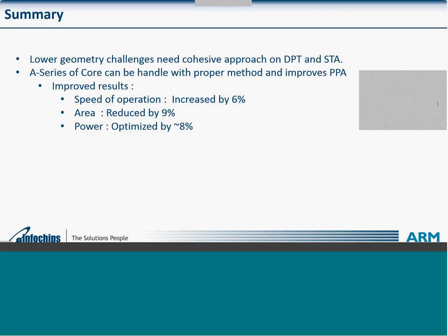A couple of challenges. Especially if you want to optimize in more advanced technology like 16 nanometer or 10 nanometer, we should be really careful because of the DPT rules. Because of DPT, as we've seen in other projects, the routing gets derouted a lot to solve the DPT-related DRCs.